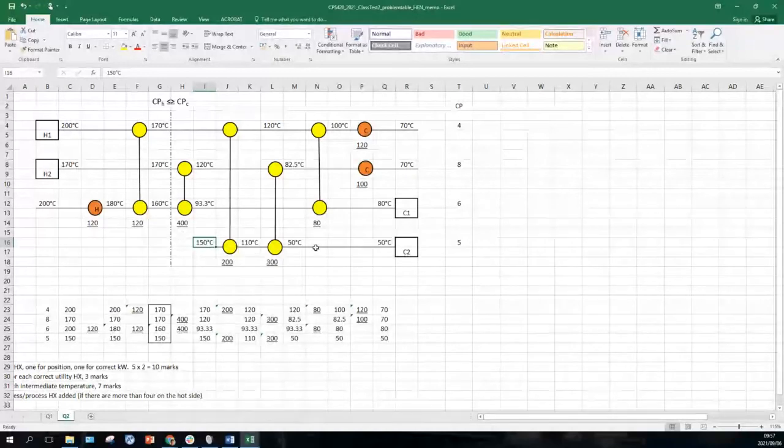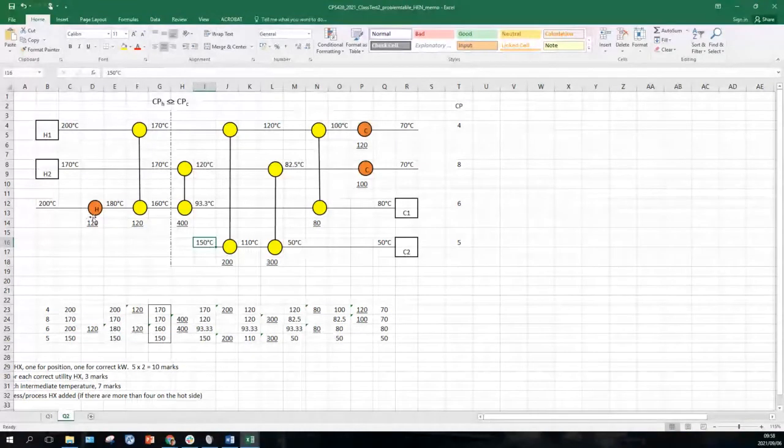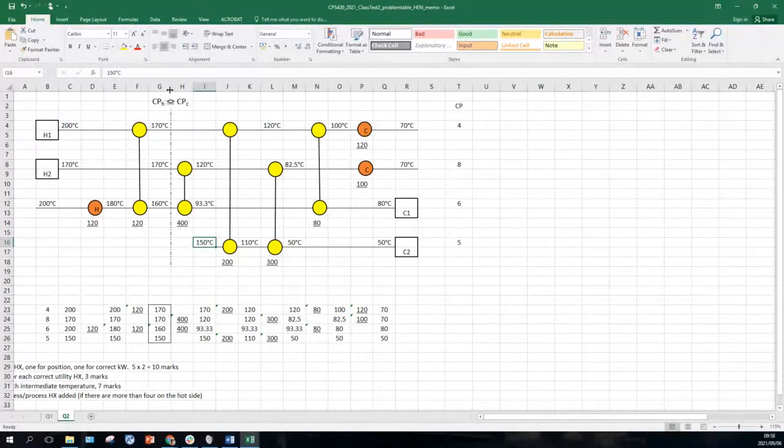That is much better. Okay, so the C2, we're not going to draw the horizontal line right through because otherwise we're going to get confused over here. We see that it only gets to 150 and the cold pinch temperature is 160. Right, cold one starts at 80 and goes to 200, so we can draw that right across. Okay, draw in the pinch. Boom, there it is, 160,